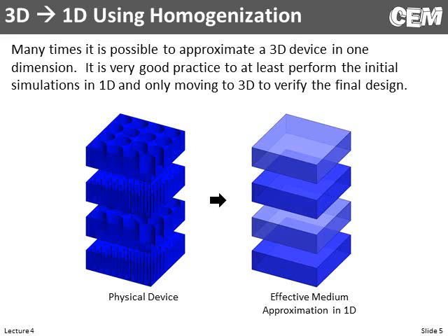All real devices are 3-dimensional. Any time that we can take a 3D device and reduce it to 2D, it's always good practice, and if we can reduce it to 1D, that's always good practice. A lot of times we'll have a slab of material. These colors are horrible, and I keep needing to re-render this. But we have big holes and not a lot of dielectric left here, right? So a good approximation to make is that this probably has a lower dielectric constant because it's mostly air.